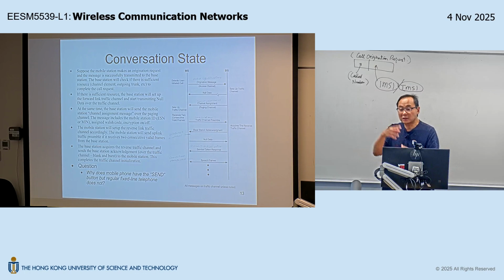So let's say the base station looks through the available downlink channels and decides to spread the traffic channel using W60. But the mobile station as a receiver doesn't know the right code, right? Remember, successful despreading requires knowledge of the right code and the right time. The mobile at this point just knows the correct despreading timing because the mobile has despread the pilot channel successfully. So it knows the right despreading timing. But the mobile doesn't know the despreading code for the traffic channel.